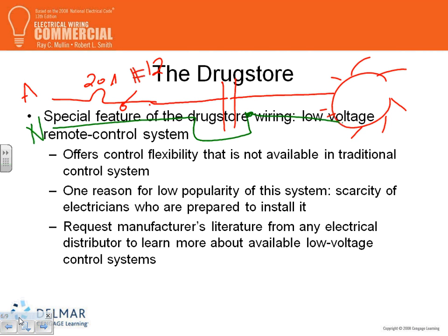This is just showing the power part of it. Let me show you the rest of the story. The rest of the story, this is, guys, the power. This light is, let's just say, 100 volt-amp light, and fed. I'm just showing one. It could be multiple of them. In reality, it would be another light over here, and you can tap from this side and tap from this side and feed another light. You have two lights now fed from a 20 amp circuit and controlled by a contactor, a relay.